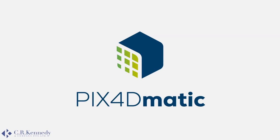So now on to what PIX4Dmatic is, and it's a software optimized for accurate and fast photogrammetric processing for corridor and large scale mapping. It's designed to handle and process thousands of images with ease while maintaining survey grade accuracy.